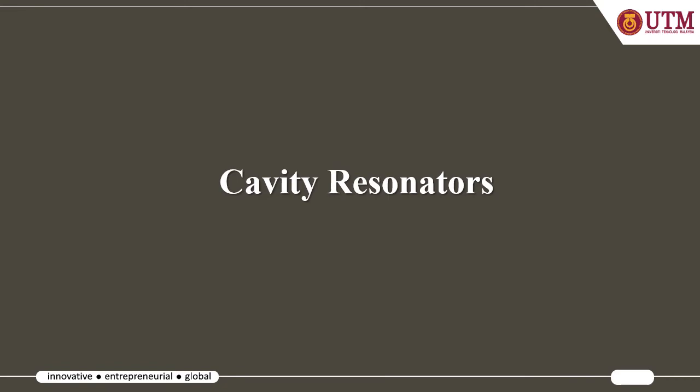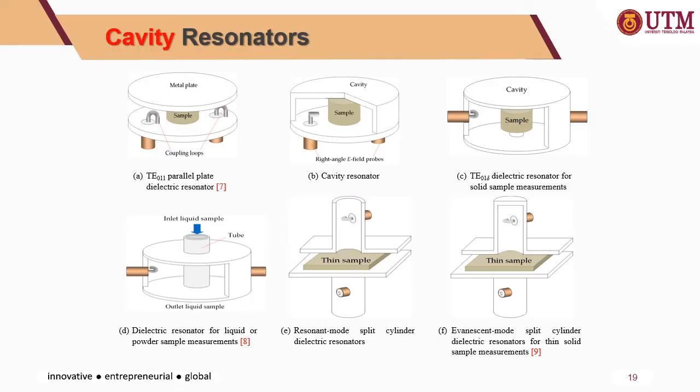And another one is the cavity resonator, and this has been done in the second year PBL lab, microwave lab, in which for the cavity resonator you have two metal plates separated by a cavity or empty space, and this technique is usually used to measure the permittivity or the property of the samples or the materials.